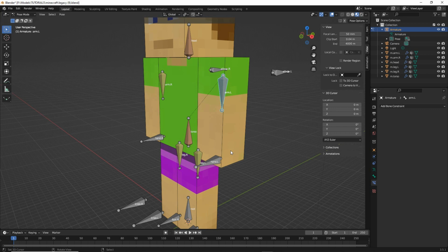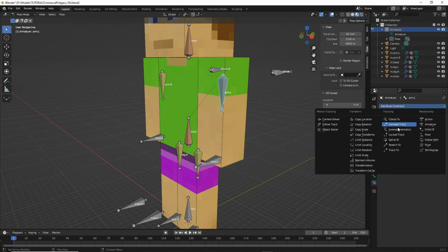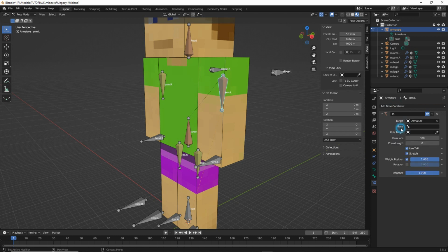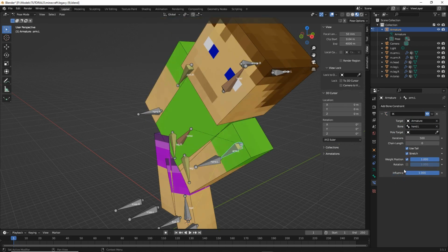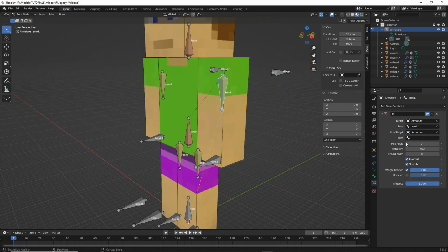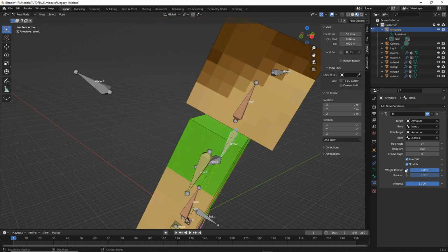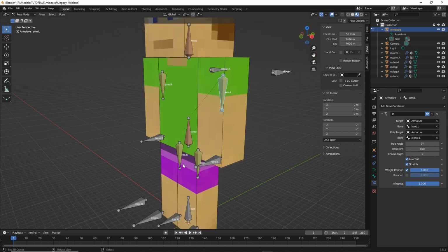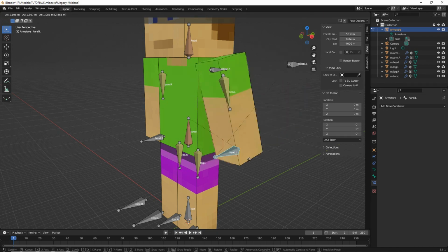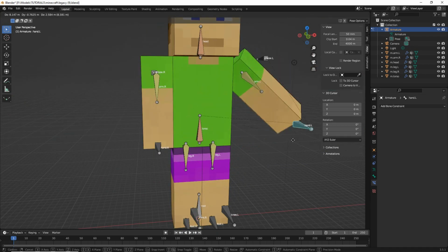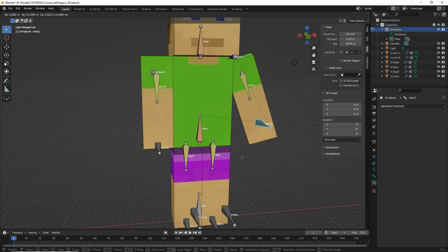the underlying bone. So repeat the process, select the arm, constraint, IK, armature, this is hand.L, makes the armature go wonky, pole target, armature, bone, elbow.L, makes the armature go wonky, increase the chain length, so now we can select the hand and move the arm.